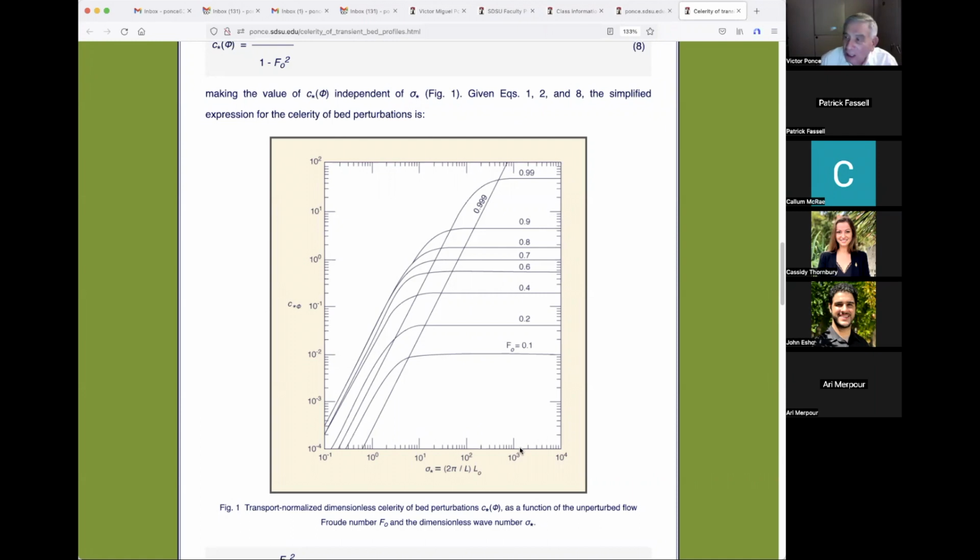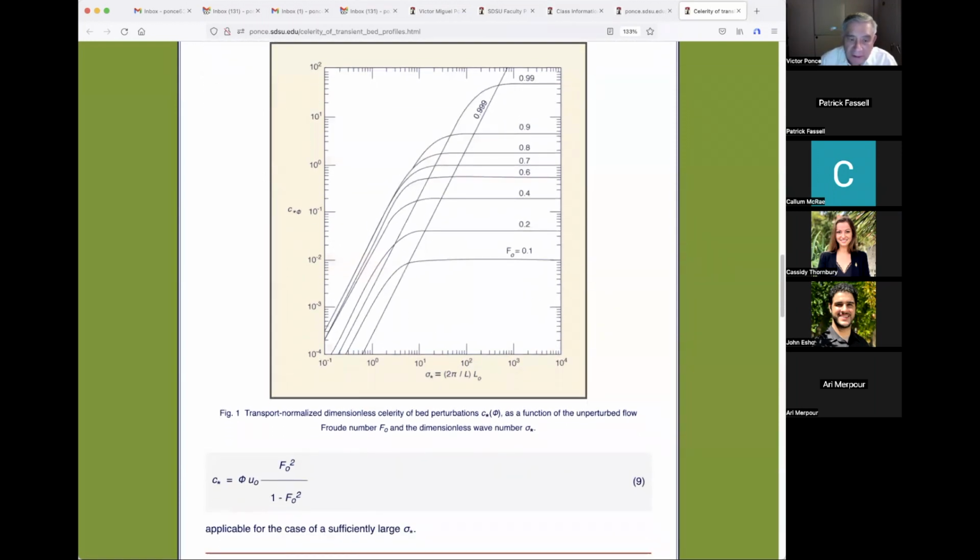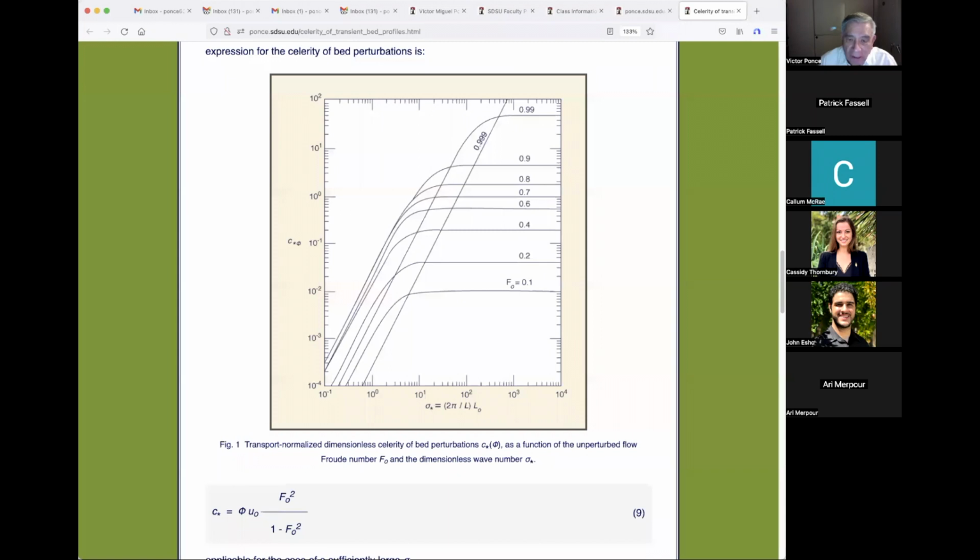And we should also mention at this point the concept that was developed by, God, I forgot his name again. The gentleman that said that natural rivers don't get a Froude number above 1. They don't even get to 1, he said, because it's impossible. The statement is that Mother Nature doesn't like natural rivers with Froude numbers greater than 1. That's what he said. And I truly ascribe to his statement, because we have studied this extensively. And by the way, this is also part of the exam. So pay attention to what I just said.